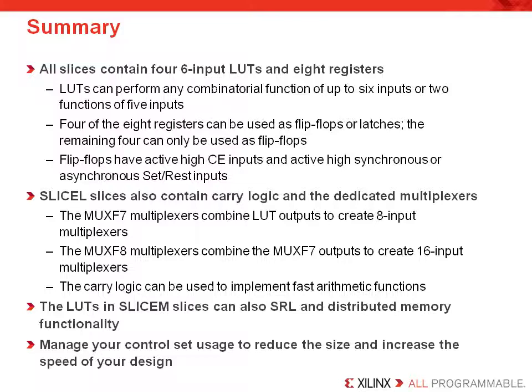SLICEL slices also contain carry logic and the dedicated multiplexers. The MUXF7 muxes combine the LUT outputs to create 8-input multiplexers. The MUXF8 muxes combine the MUXF7 outputs to create a 16-to-1 multiplexer. The carry logic can be used to implement fast arithmetic functions. The LUTs in the SLICEM slices can also create shift register LUTs and be used as distributed memory. And finally, manage your control set usage to reduce the size and increase the speed of your FPGA design.